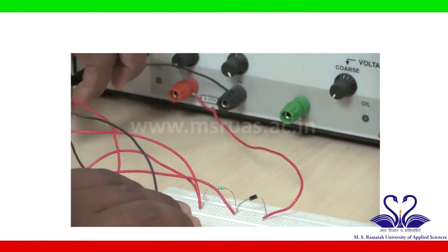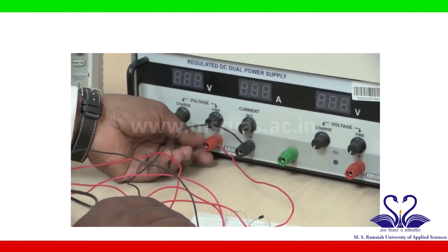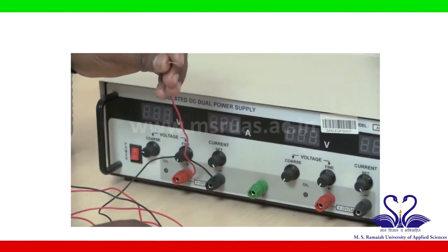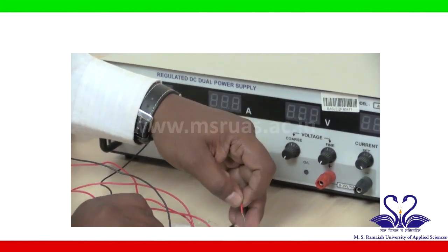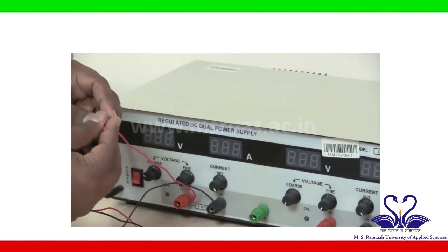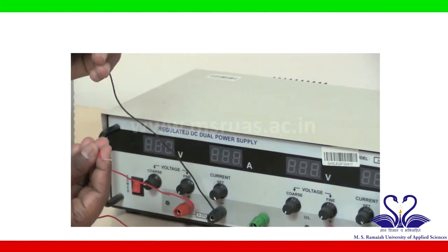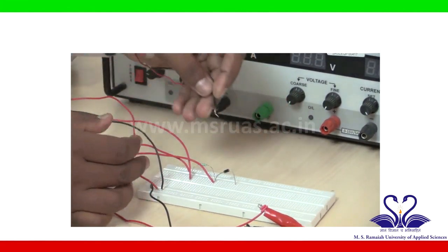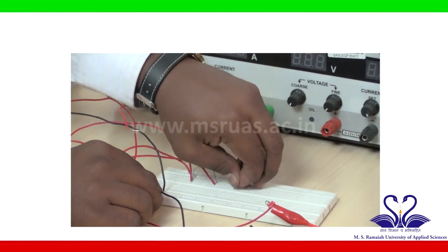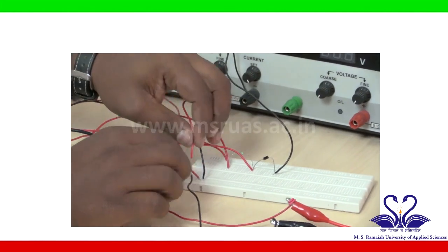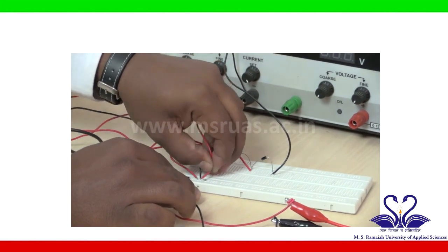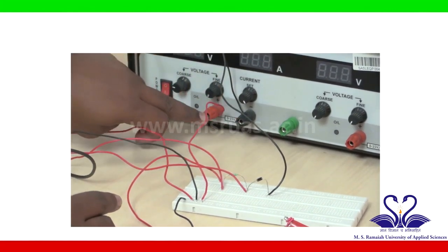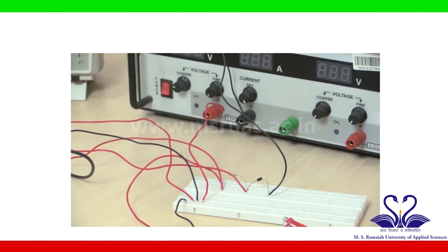Similarly, I will reverse the terminals of the DC source. It can be done like this. So this is the positive which was earlier connected to the P side of the diode, this is the negative which was earlier connected to the ground. Now I will reverse these two terminals: negative I will connect to the P side of the diode and positive I will connect to the ground. Just by reversing the diode direction and voltage terminals, this will be the circuit connection for a negative shunt clipper.